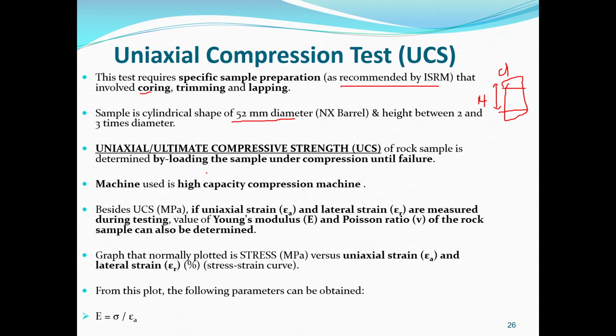The load will be applied until failure, and the best thing about this testing is that we are able to measure the axial strain and lateral strain, and then when we get the lateral and axial strain, we can get the value of the modulus and Poisson ratio.